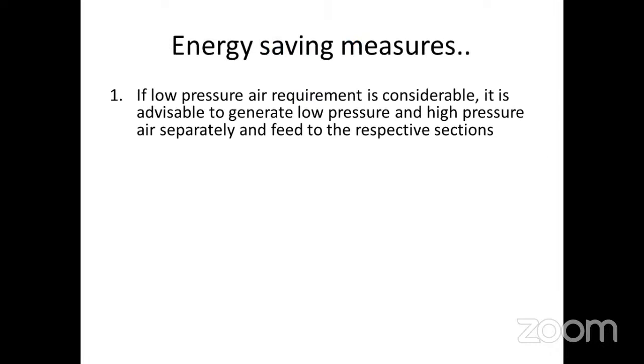Energy saving measures. If low pressure air requirement is considerable, it is advisable to generate low pressure and high pressure air separately and feed the respective sections.